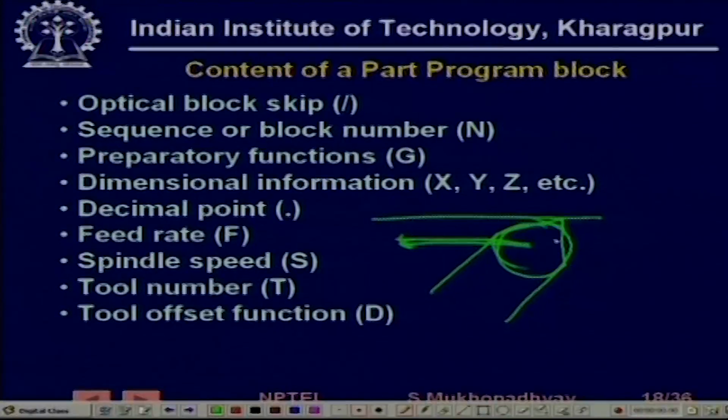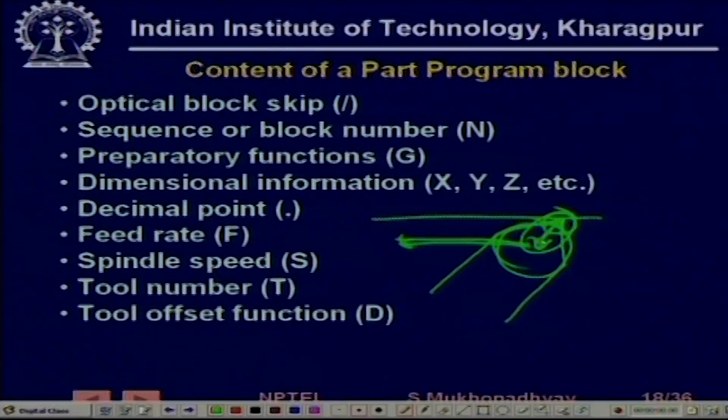When the tool moves, because of this, there is some distance between some logical center of the tool tip and the actual point where it is making contact, and it's not only making contact, it's actually gradually getting worn away. So, this length is actually changing, it's shrinking. So, various kinds of offsets are produced when you are giving the motion. You have to give the motion to the tool in such a manner that after taking care of this finite tool head situation, the right parameter will be obtained. Therefore, the tools must be a little bit offset.